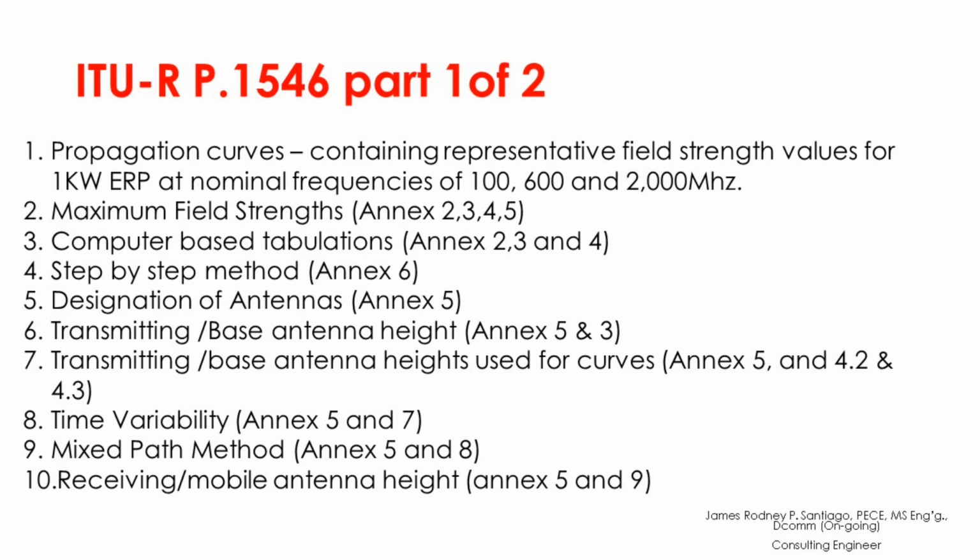So you can actually check those propagation curves inside this recommendation, downloadable on the ITU website. The curves are based on a standard 1 kilowatt ERP at nominal frequencies of 100, 600, and then 2000 megahertz respectively. Next would be the maximum field strength values on Annex 2, 3, 4, and 5.